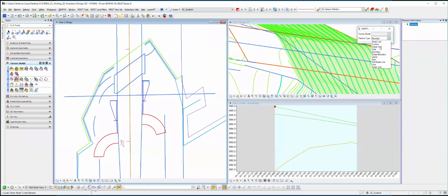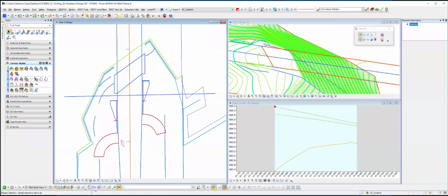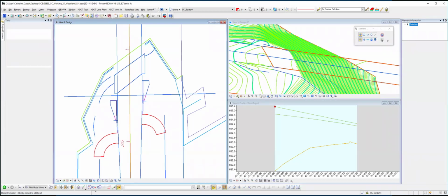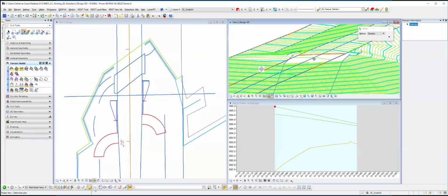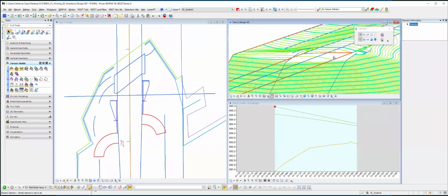which is a drape void. So it actually pulls its elevation from the terrain model that it's going to be connecting with. So I'm not altering the elevations here whatsoever in that cutout area. I'm just using that shape to determine where I want to gap the surface model. Okay.